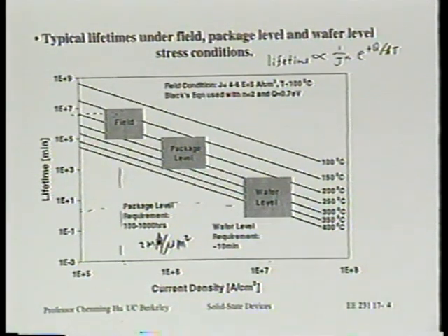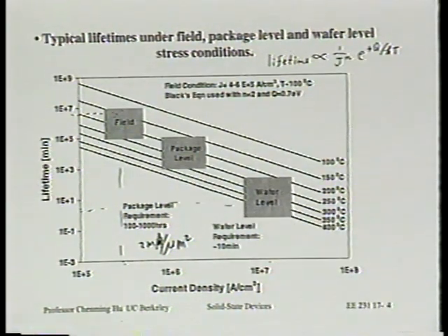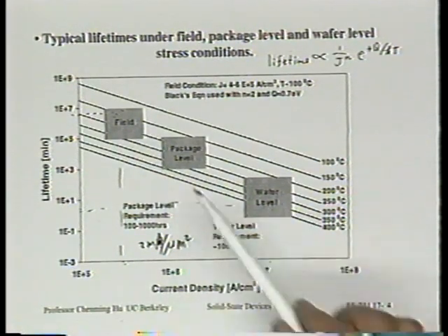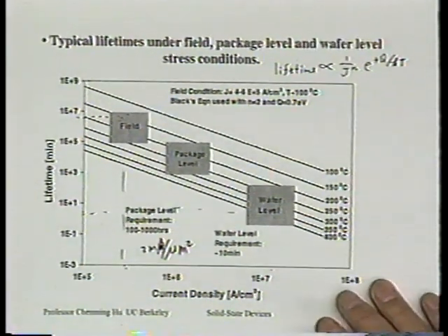In that case, you can get an answer within minutes, truly. But then there's less confidence to extrapolate that data. We don't know whether the mechanism of electromigration truly remains exactly the same, or perhaps the activation energy changed when the temperature gets that high, or when the current density gets that high. You see that? So this is an issue the engineers often have to deal with.